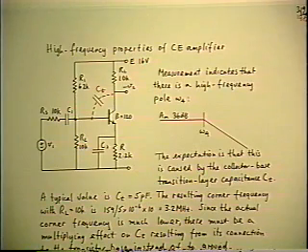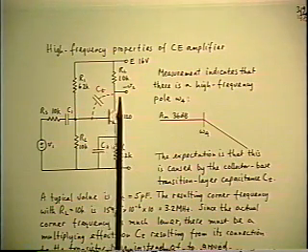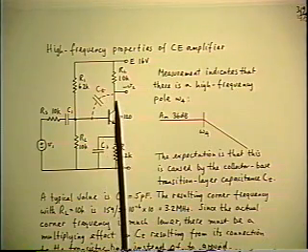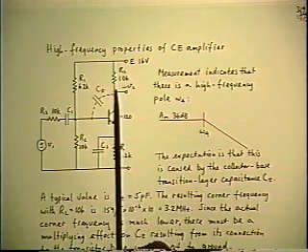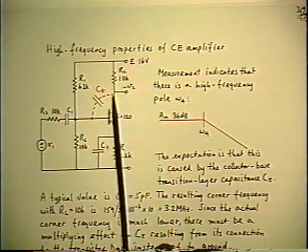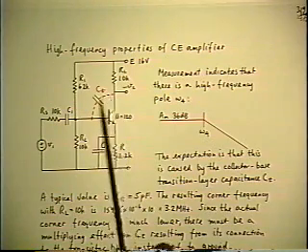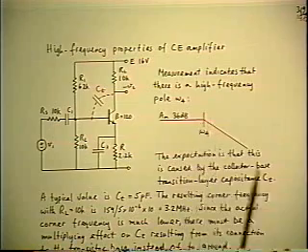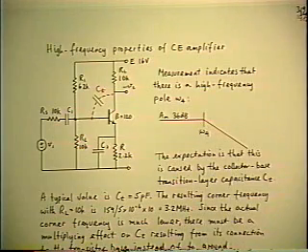So at a very rough first order sort of guess, you might think that this would cause the pole because the output collector current of the transistor, which is supposed to go into the RL in order to provide the output voltage, is partially being diverted through the CT. So less of it goes into the RL, therefore the gain starts to drop off at higher frequencies.